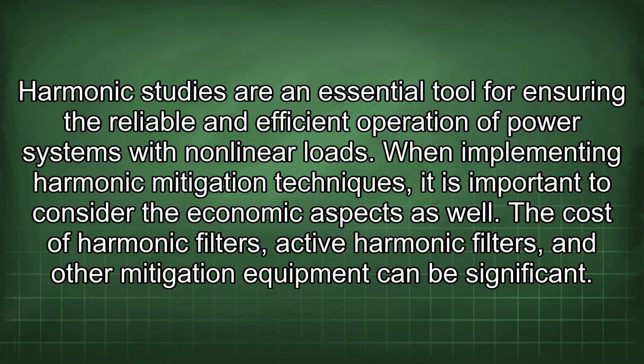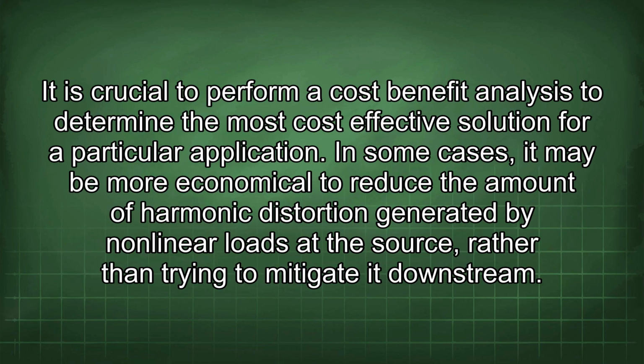The cost of harmonic filters, active harmonic filters, and other mitigation equipment can be significant. It is crucial to perform a cost-benefit analysis to determine the most cost-effective solution for a particular application. In some cases, it may be more economical to reduce the amount of harmonic distortion generated by nonlinear loads at the source rather than trying to mitigate it downstream.